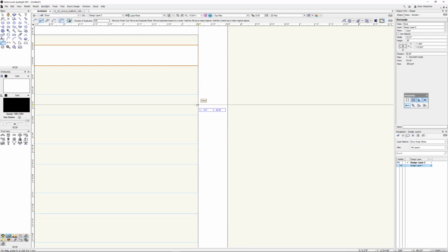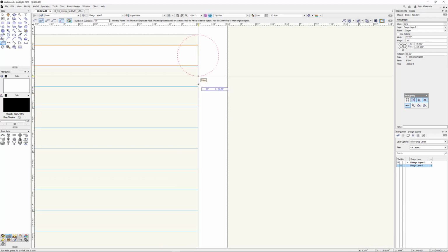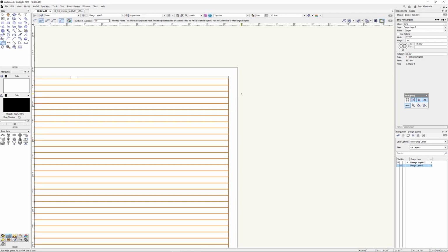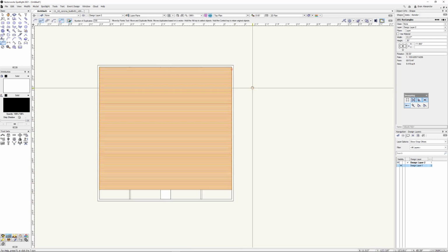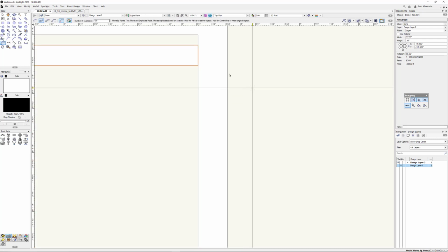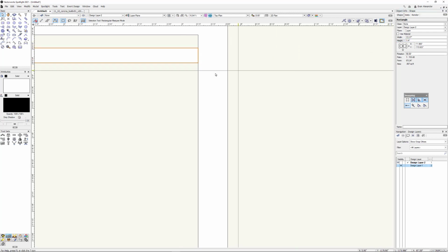All right, so now if I hit tab for length, this is 8.9 millimeters, and I hit enter, this is now going to lock us in, and then we're going to say okay, and click. Oh, nope, you know what? That is not right. Why is that not right? Maybe this is too thick. Let's make it a quarter inch. And then what did I do wrong here?